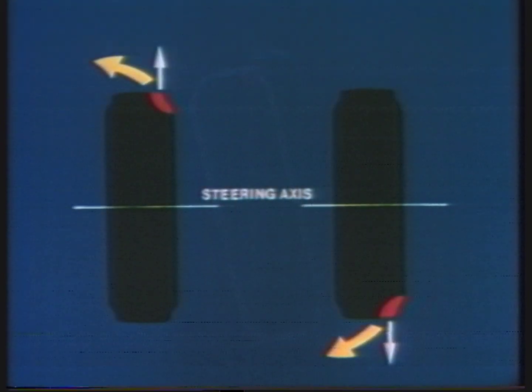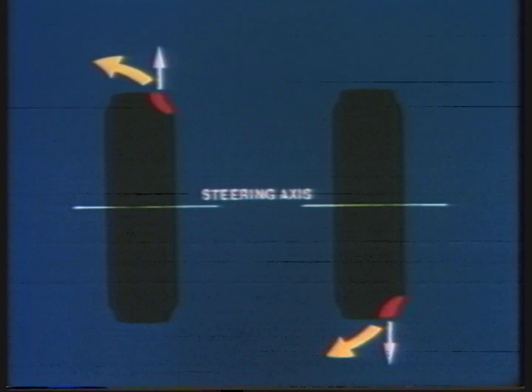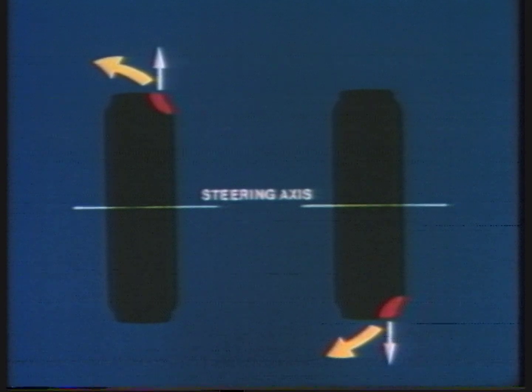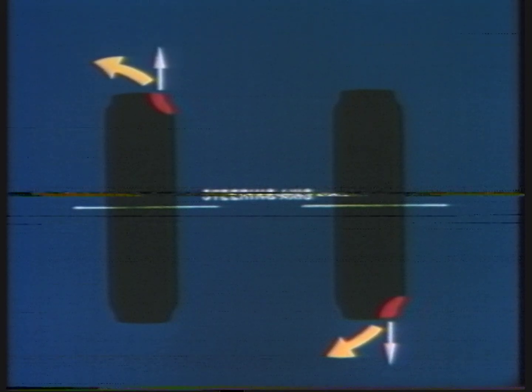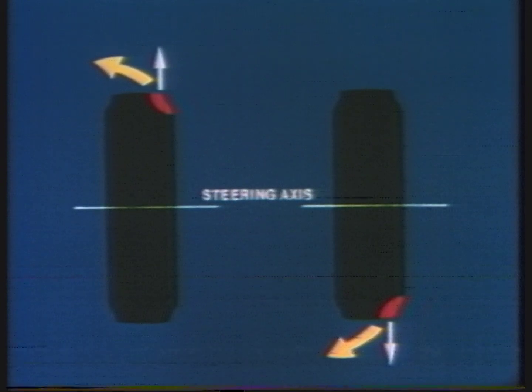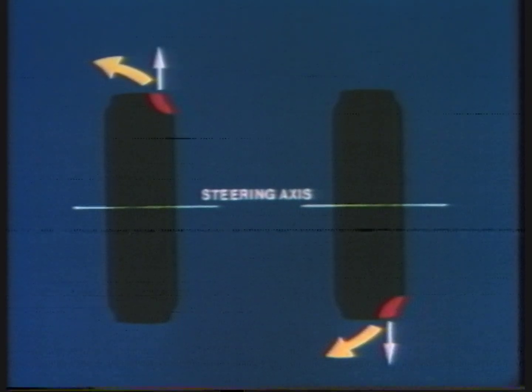As the effect of twisting about the steering axis is reversing the thrust at the steering wheel for every revolution of the road wheel, the predominant sensation, apart from vibration, is a shimmy or wobble effect felt at the steering wheel. While the tramping action of kinetic unbalance is still present, it may not be noticed. Dynamic unbalance can be created by incorrect tire fitting causing runout.